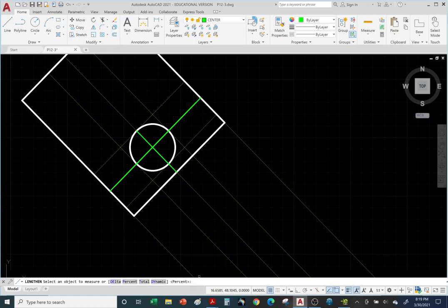So let's go 75%. Instead of 100, we'll go down to 75. Enter percent. Oh, let me do it again, percent. Click on the word percent, type in 75, and enter. So we're going to reduce the length here and here. Ta-da! All right, so hit escape to deselect.